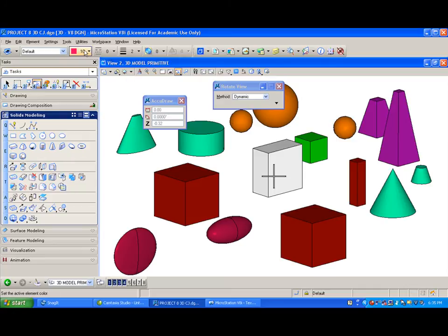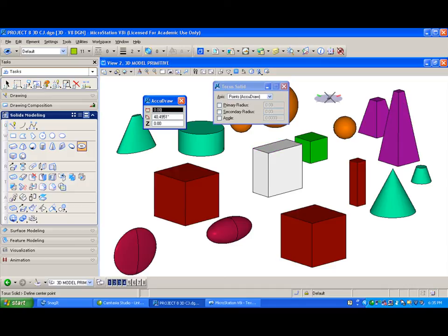Next we have, these are starting to get fun, so we'll go to a torus, donut, inner tube, whatever you want to call it. This one's a little more difficult. It says enter a start point. So I enter start point out here. And it says define a center point. Well, we'll define a center point back here. And then it says define angle and secondary radius. So this takes a little bit of mouse work. So you can take this, you pull it straight out, and then put in a secondary axis, which might be, say, 0.6.